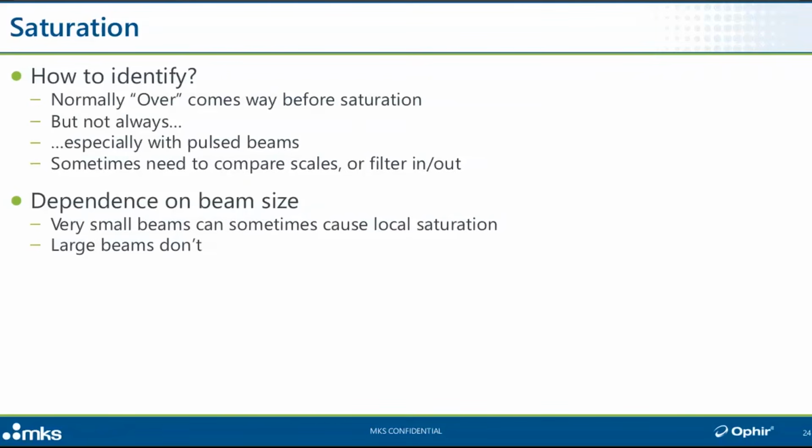There's no clean-cut answer. The only real way to do this is, to a certain extent, to depend on your intuition. So if you sense that something doesn't look quite right, what you do is you go to a one less sensitive scale and compare. Let's say you're on a 10 milliwatt scale and you're measuring what you're expecting to be 8 milliwatts, and it's telling you 6 milliwatts. I'm just making up numbers. And you're not sure. So what you can do is you go down to the next less sensitive scale.